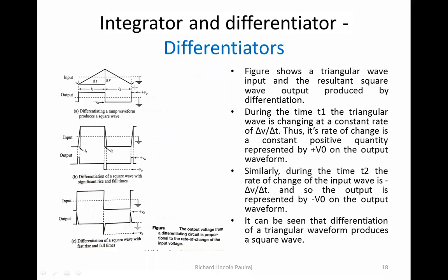You can rig up the circuit in your labs, or probably using simulators. We have spoken about simulators previously. So you can just rig these up and check what happens if you give a square waveform, and what happens if you give a triangular wave. Here I have taken the example of a triangular waveform, and we are obtaining a square waveform output.